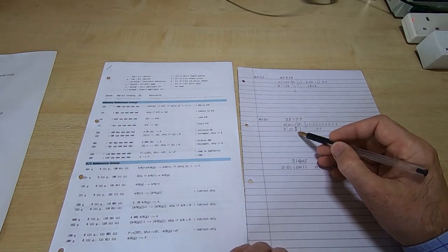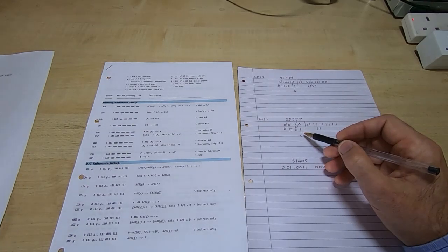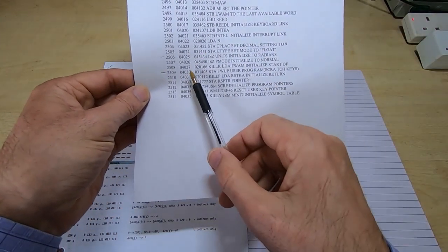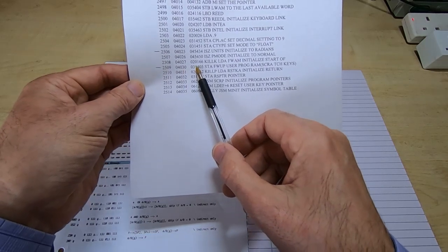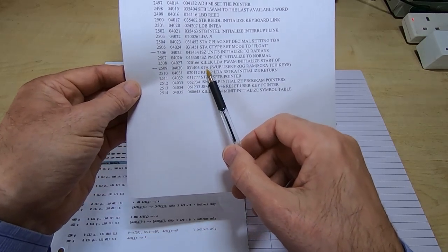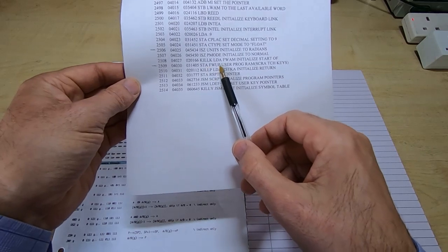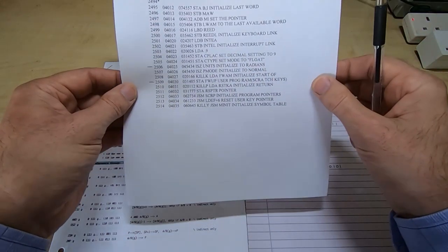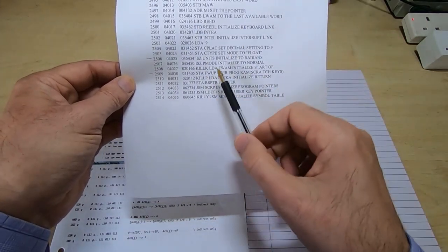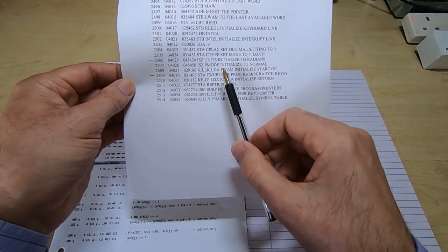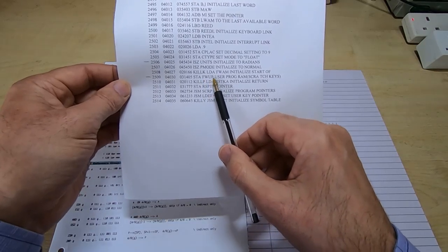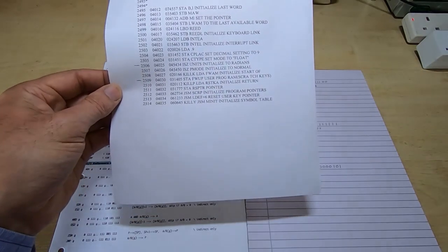Okay, so this should be a store B instruction if this is correct, and if we look at the listing for address 4030, we'll see it's supposed to be a store A. Not only that, but it's store A of this value. This is, if you like, a disassembly of the code. I don't know how accurate this is, but in the grand scheme of things it should make some sense. And if we look up the address for FWUP, which I've done,